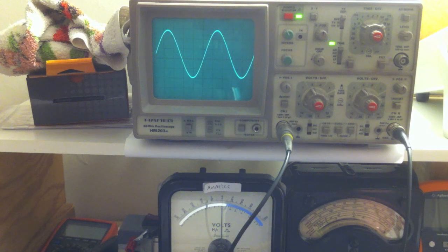Now when we're increasing the resistance, I'm going to start switching up the decade box, and by doing that I'm slowing down the charges that are accumulating on the capacitor. When I slow down the charges accumulating on the capacitor, that means I'm going to increase the delay, because it's going to take longer to charge the cap up. Therefore, when we look at this curve, we'll eventually see two curves.